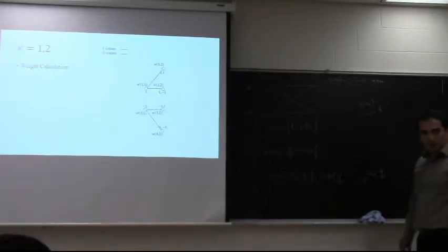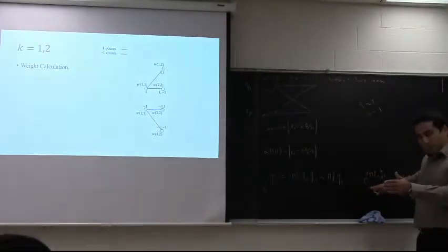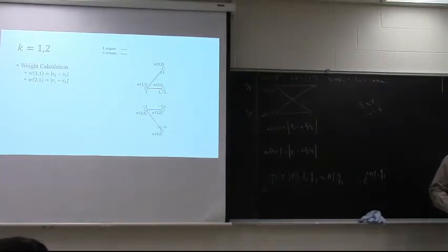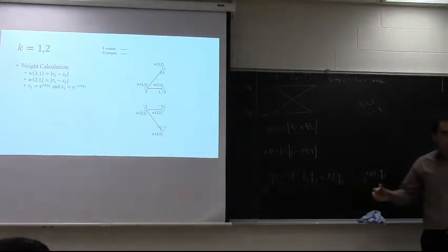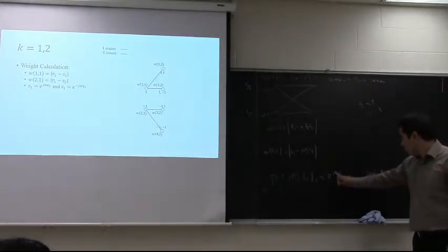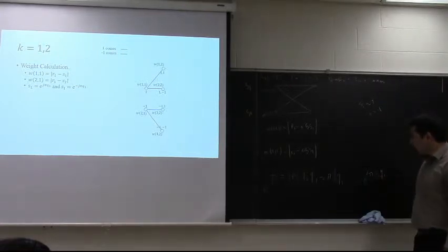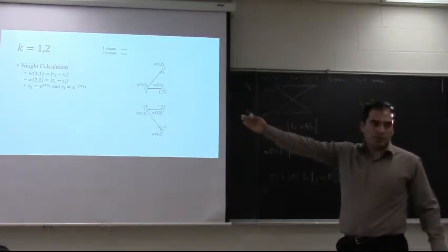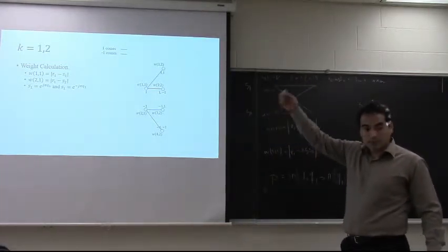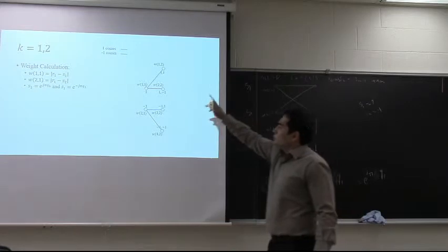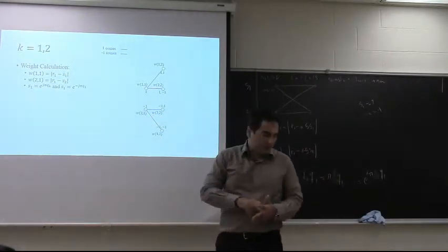You have transmitted this one. The weight is the distance between the transmitted symbol and the received symbol. Therefore, W11 is R1 minus S1, where S1 is e to the j pi. What is I0? For the first one, do nothing. And for the second one, because you are transmitting minus 1, it is e to the minus j pi q1. This is the first step of the Viterbi algorithm for the GMSK signal. Okay, you have this one, that's fine, you have this one, great.